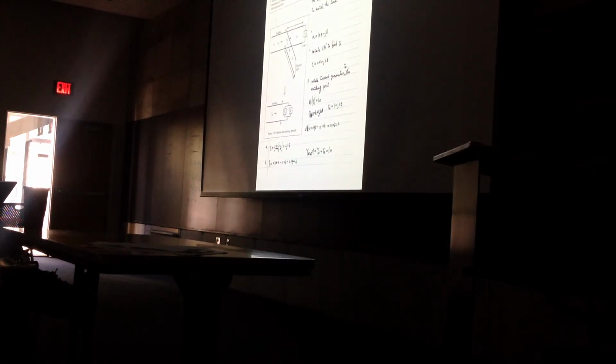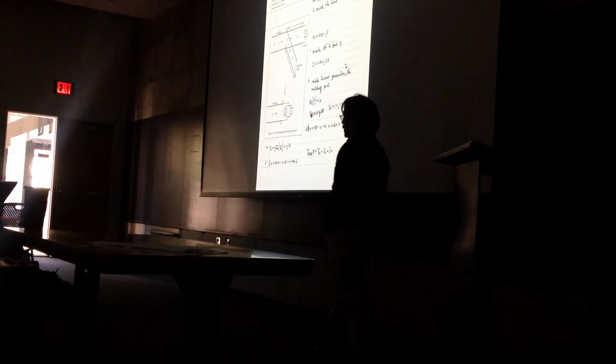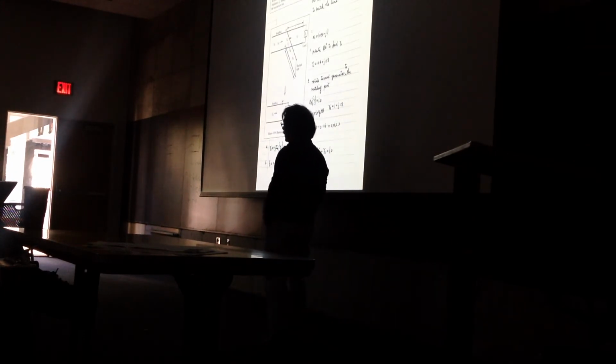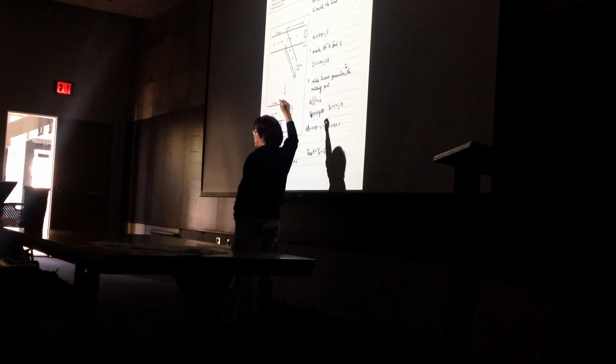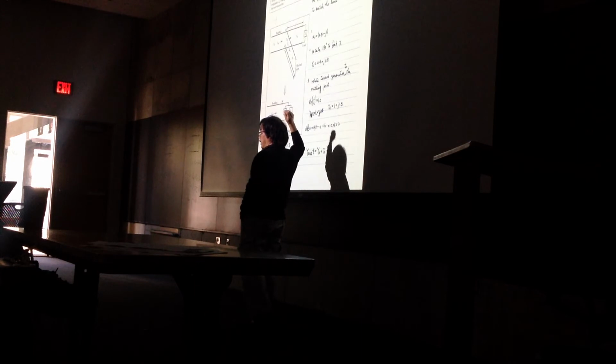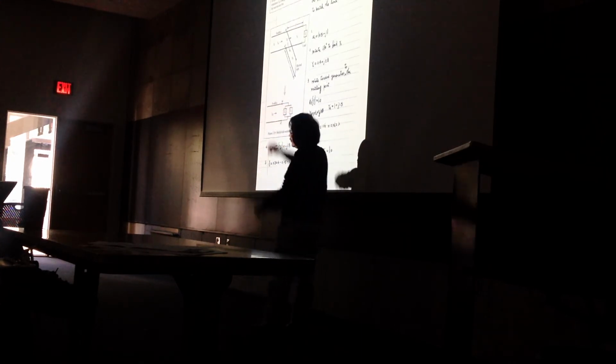So here is what we do. You can use a short circuit or open circuit transmission line and, by adjusting the length, it will become an inductor or become a capacitor at the location. In this particular example, we are using the short circuit transmission line to behave like the inductor at the location. So depending on the length that you have, it's going to be either inductor or capacitor, depending on the length of the transmission line.